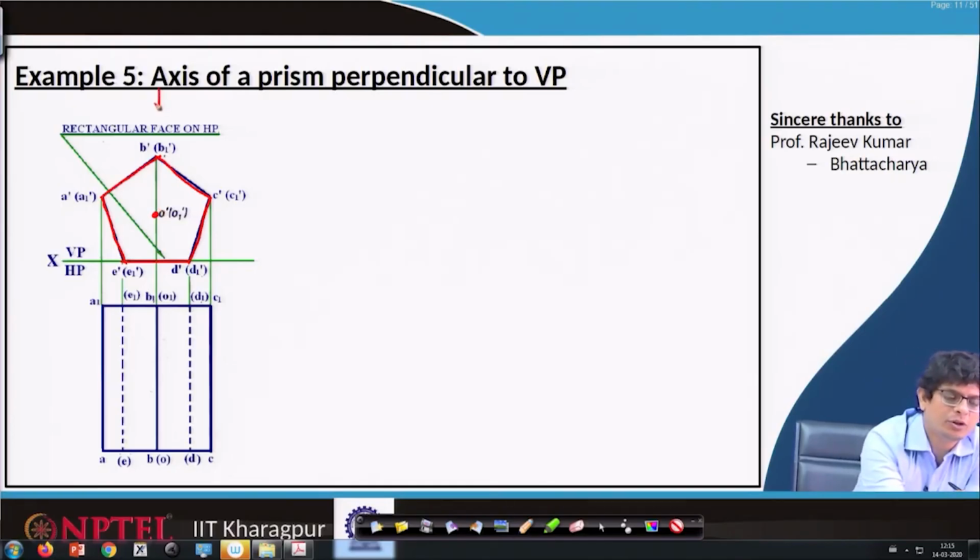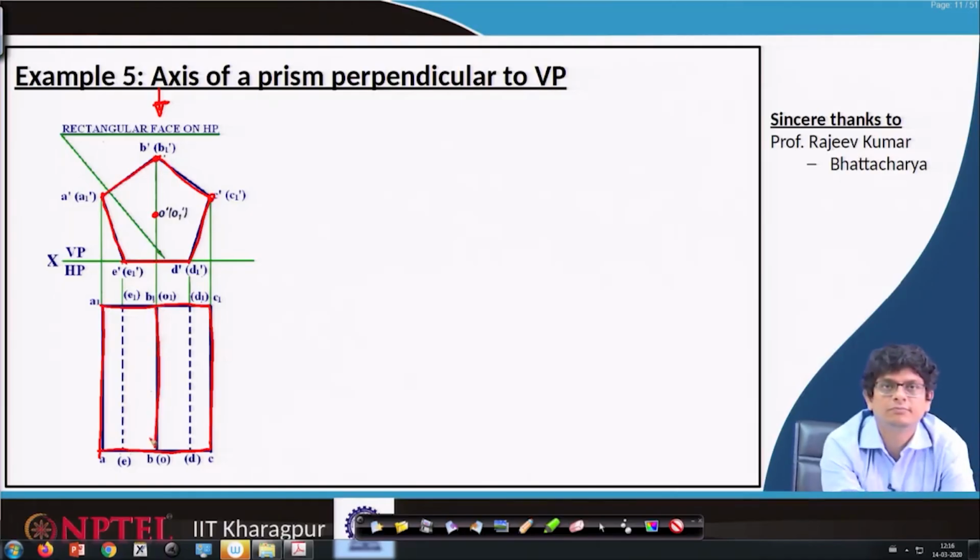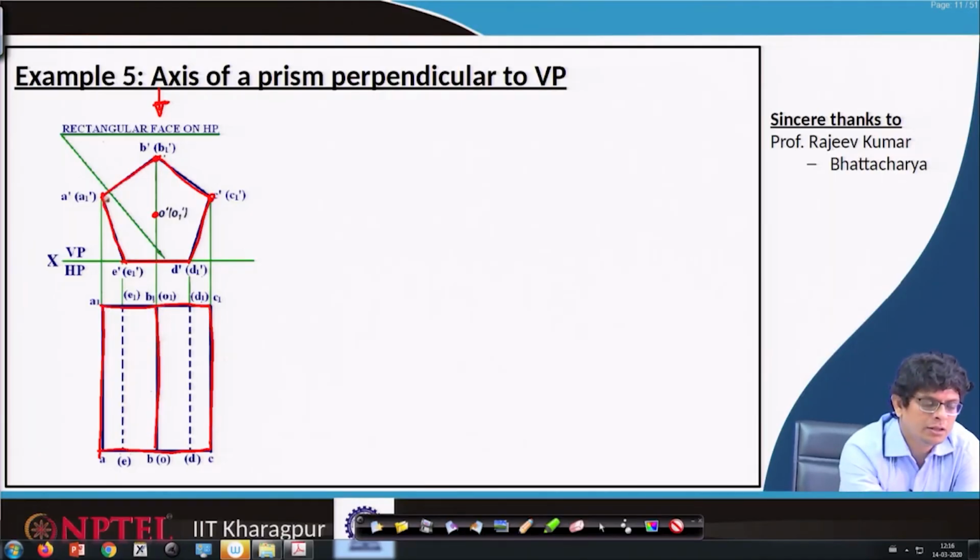When we are looking from top view, these points map to lines, like edges, and we will see that, and this line entirely from the top view again is a continuous line. This one will be visible, maps there, but these points or those edges will not be visible. So, we show it by dashed lines.